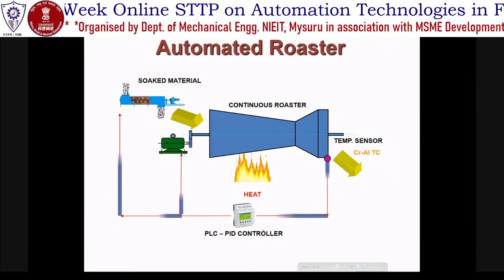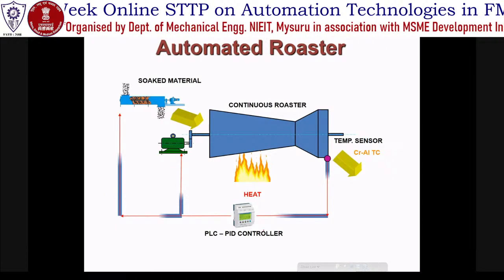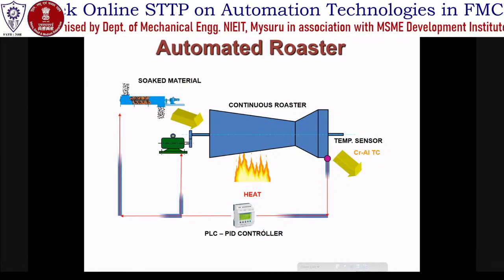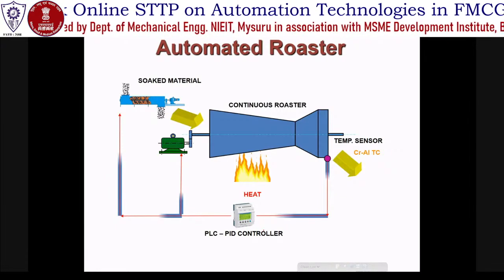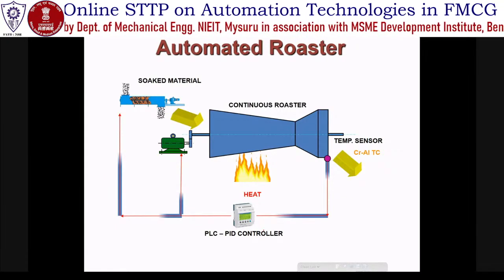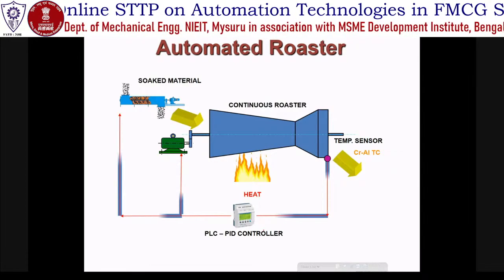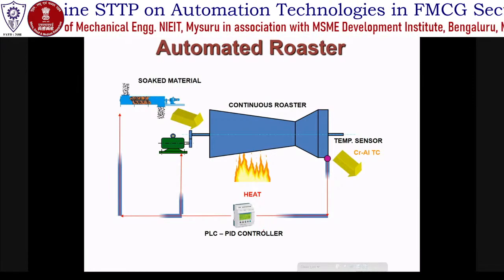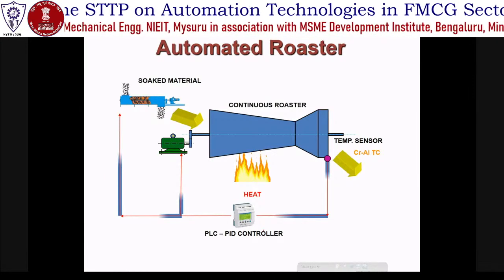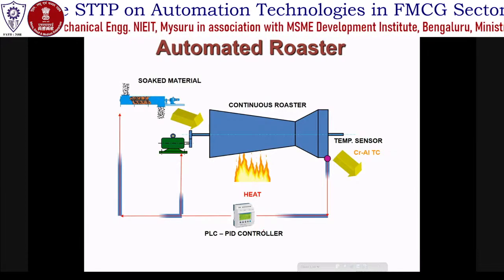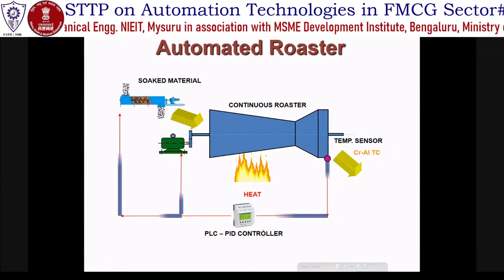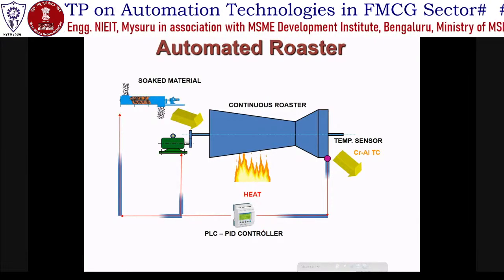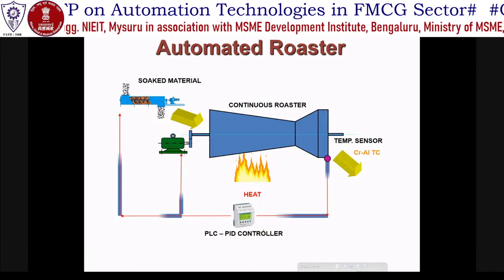Now, how do we know what the gap is? We use what are known as LVDT sensors, linearly variable differential transformer sensors. They were put onto the elements of this roll to see the gap between the rolls, and the gap was displayed on the computer. So a non-automatic system was automated using available components. This is another piece of work that has been done at our institute. This is just an example to show how we can make use of our basics to bring about automation.